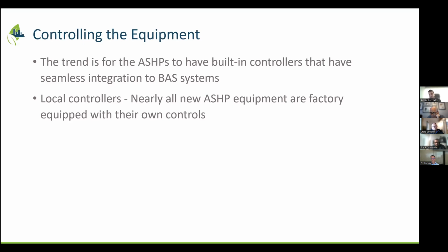So in general, the majority, if not every single one of these devices are now coming with a factory controller in there. They're complicated machines with refrigeration cycles. They need to be controlled by the people who manufacture them because they know how to control the inner workings of that machine best. With that being said, and Craig touched on this multiple times, I think the biggest takeaway here is, integrating to a piece of equipment is not really a hard thing anymore. Connecting BACnet IP, BACnet MSTP, that's the easy part.